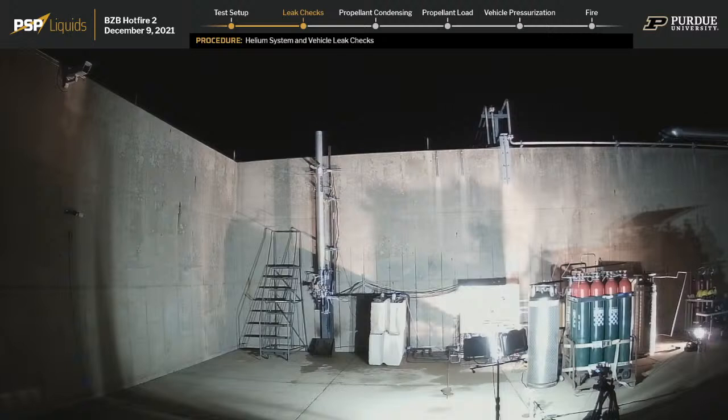So purges are a really important part of working with any kind of rocket system, especially one involving liquid oxygen. Foreign object debris, or FOD, is a really big concern when it comes to any kind of rocket system. Anything that you don't want in your system can cause really big problems if it's left in there. So what we do is we flush a bunch of nitrogen gas through the system, and this will remove any kind of particulates and atmospheric air, including water vapor, that would be present in the system. This is really important when we get down to cryogenic temperatures, because that atmospheric water can actually freeze and clog things up.